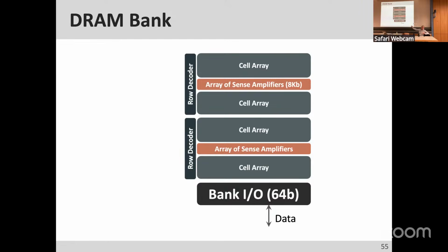So this is a much bigger interconnect, because if you think about the sensing from the cell array inside the subarray to the sense amplifier, that's a shorter interconnect, but a lot of wires, shorter but high bandwidth. To get the data out of the DRAM chip, normally you don't have 8 kilobits of wires. You actually pick, let's say, 64 bits, sometimes even smaller.